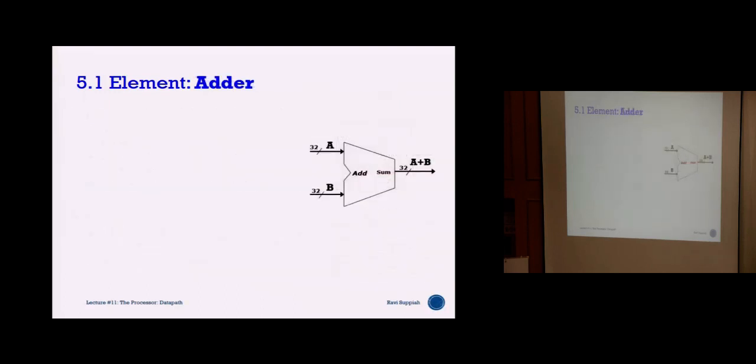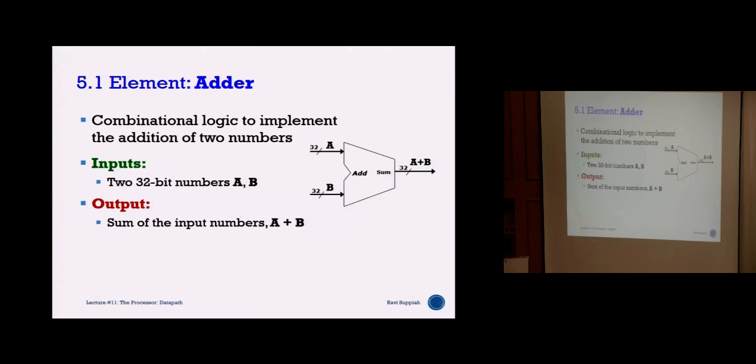Your adder is a hardware adder, and we say it is a combinational logic. When we say something is combinational, it means it is not triggered by any clock. That means as long as I provide some data here, FF, and so on, as long as I present some data to the hardware, it will perform the operation and give me the output. There is no clock trigger, there is no code executor, nothing. It is just a hardware block. Input is provided, the hardware will trigger, and I will get the output. In this case, it's nothing more than adding two 32-bit numbers.